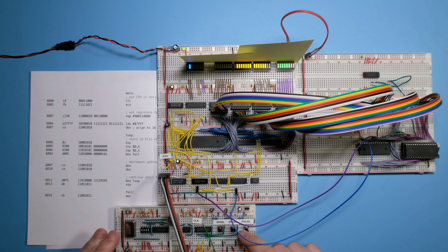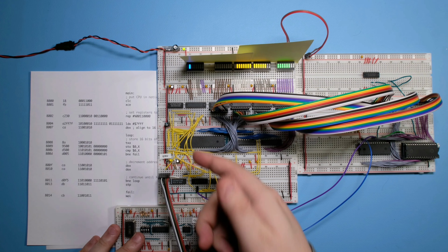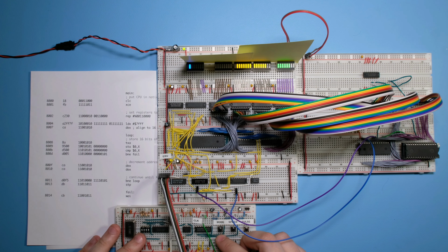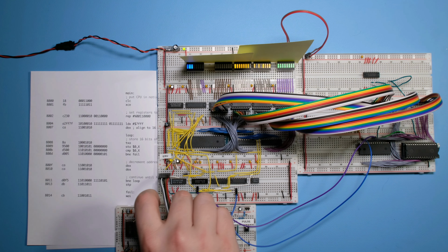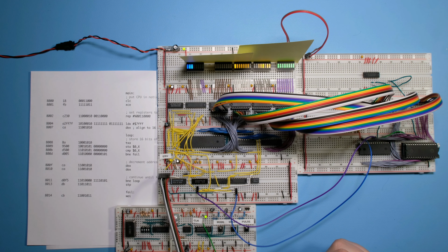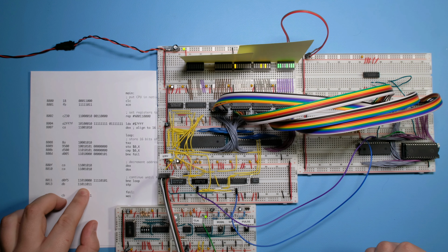Okay, so I'm going to let the program run, and then it should stop the CPU when it's finished, and if there's an error, it should raise the wait line. So let's do that. So this is running now at the maximum of the slow speed, but it's still pretty slow, I guess, to go through 32K of RAM. So let me go into the fast clock, and it's done. And as you can see, we have reached the stop instruction here.